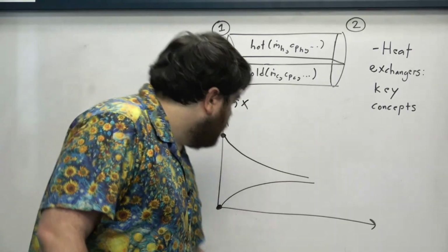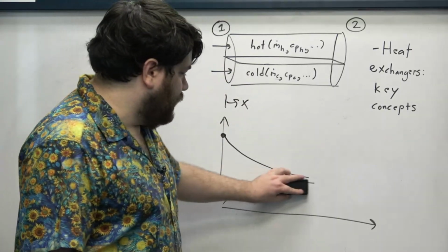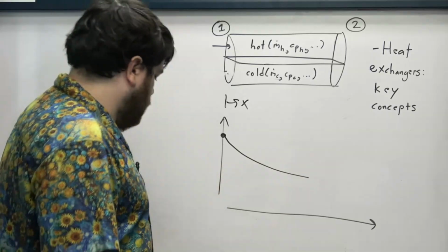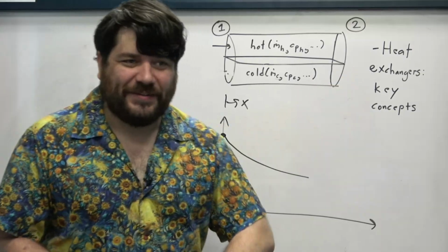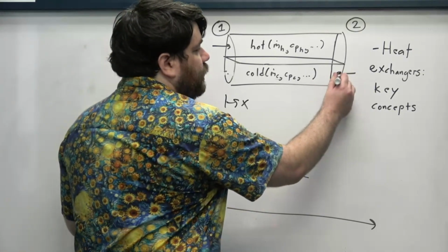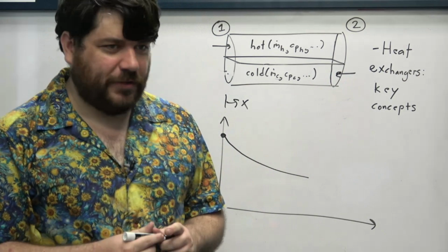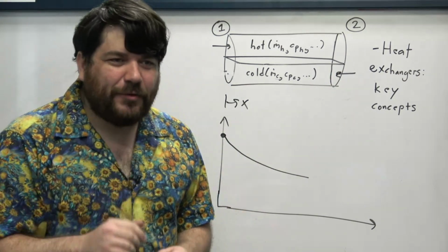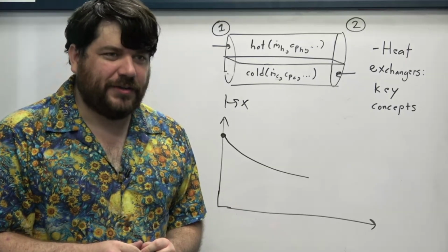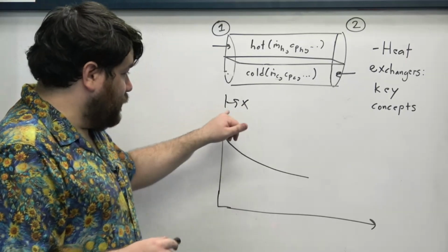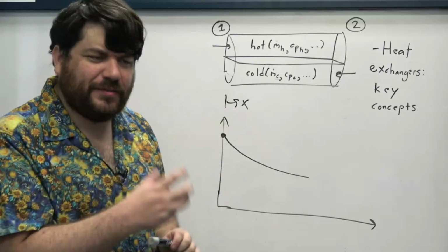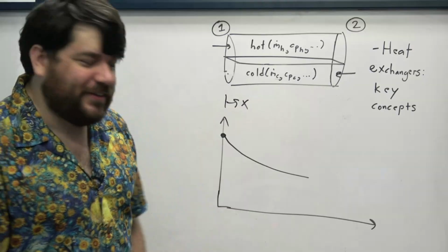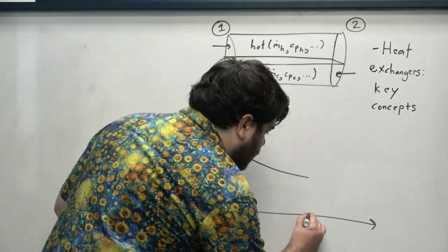Imagine what happens if instead we now make the hot liquid come in from the right, okay? So now we set up what's commonly referred to as a counterflow heat exchanger. And whenever we have a counterflow heat exchanger, the idea is that now, from the perspective of this coordinate x, the cold inlet temperature is happening right around here, okay?